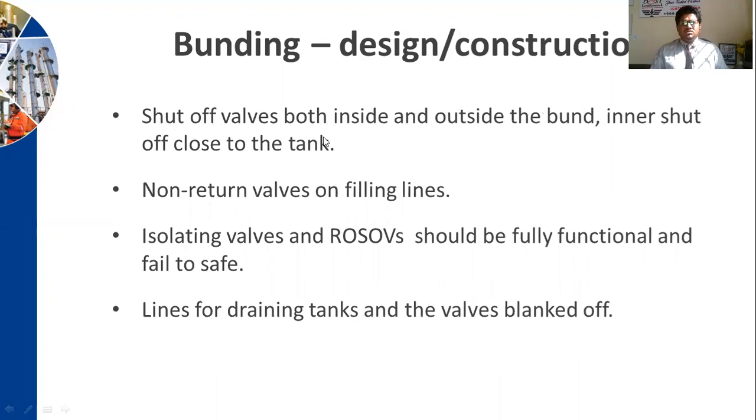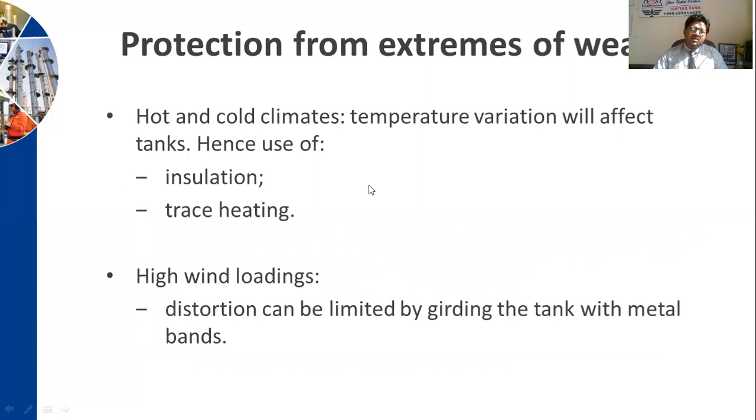Now, shut-off valves, both inside and outside the bund, are important in a shutdown, shut off close to the tank. Non-return valves on filling lines, isolating valves and ROSOVs should be fully functional and fail-safe. Lines for draining tanks and valves. So, the more technically you understand the tanks, the better process safety engineer you will be.